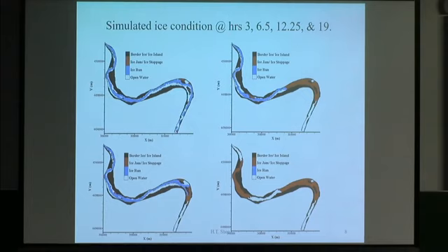As we said, ice cover on the river in the main channel always starts from ice jam or jamming of the ice. And this just shows that's the beginning, the first jam formed here. And when this jam develops, it backs up the water and slows down upstream, and then we have another cover formed with open water in between.